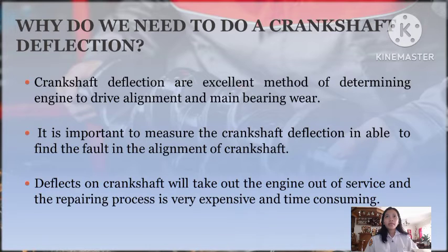I will be continuing to report about crankshaft deflection. So, why do we need to do a crankshaft deflection? First, because crankshaft deflection is an excellent method of determining engine to drive alignment and main bearing wear. So it is important that we conduct